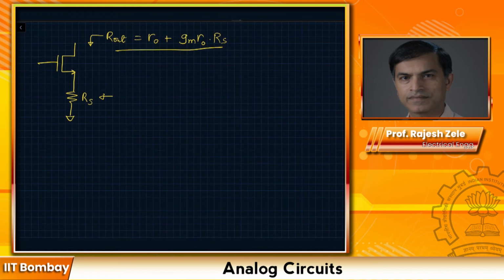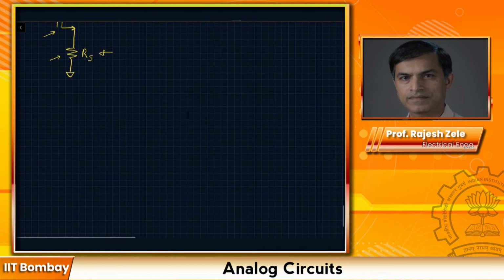In an integrated circuit environment, we may not want to use a resistance because the resistance Rs and the transistor are two different steps in the fabrication process. So you would like to use something that matches very well, and sometimes you may want to use a transistor instead of Rs to implement the resistance. So we could start with an example. First example would be, let's say we did this.